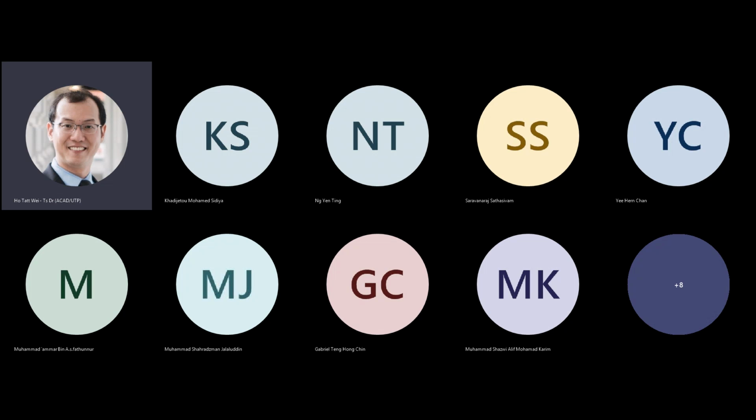This is a local computation. It's a logic computation. These are the inputs. These are all the possible mappings of inputs to an output combination. This is a local computation. And this local computational unit is synchronized with the activity of this local computational unit through a clock, right? Where does the synchronization happen? If it's an edge-triggered flip-flop, the synchronization happens at the edges. So in this case, positive edges, or if you have negative edge-triggered flip-flops, it happens at negative edges. Why? Because it doesn't really matter how, well, but it matters. Let me take that back. It matters. We'll talk about that pretty soon.